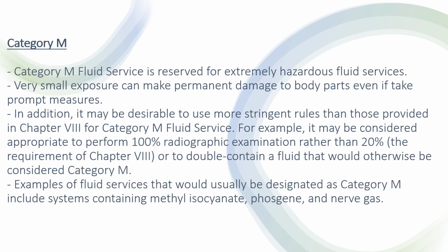The next one we discuss is category M. Category M fluid service is reserved for extremely hazardous fluid service. For me, this category M fluid is really hazardous. Okay. For category M, you need to be extremely careful. If you are fabricating any pipeline through which the category M fluid will flow, then extreme care needs to be taken. Maybe 100% radiography will be proposed.